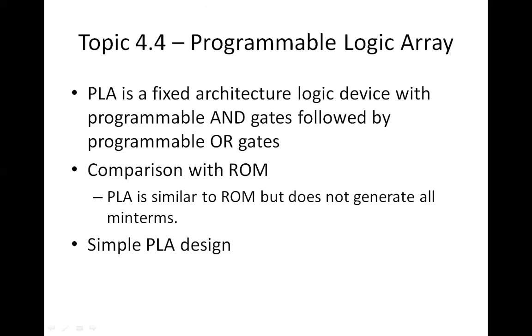Topic 4.4 is the programmable logic array, or we can say PLA. PLA is a fixed architecture logic device with programmable AND gates followed by programmable OR gates. So PLA provides an architecture which includes AND gates and OR gates. You are all aware of the AND gates and the OR gates that you have studied earlier. This is an arrangement of AND gates and OR gates which finally generates a PLA.